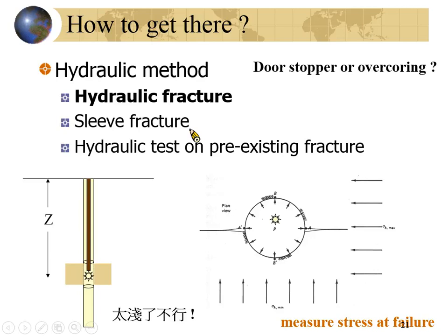You need to drill a borehole, polish the surface, and attach the strain gauge on the surface, and then drill a borehole through the strain gauge. It will be extremely difficult if you want to do it from the ground surface to measure the in situ stress at a depth like 200, 300, 500 meters.